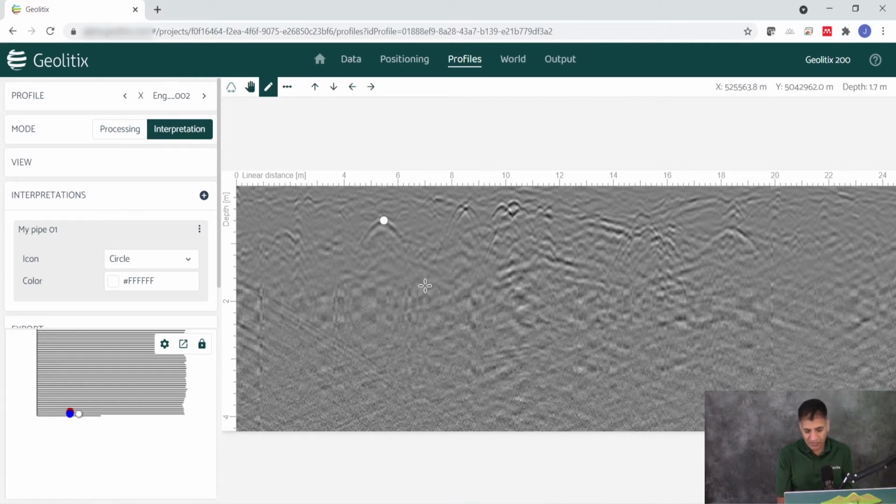So it's very rare these days that somebody's only doing a GPR survey. Maybe the utility detection company just does GPR, but so much of it is about integrating other data sets that you've collected on site, be it site observations, photographs, a drone. You might have a drone taking photogrammetry. You might have a LiDAR. You might have other geophysical methods, EM conductivity. Perhaps you're looking at magnetics or even an electromagnetic locator. All of that provides context which informs your decision making within your GPR processing and eventually your interpretation.